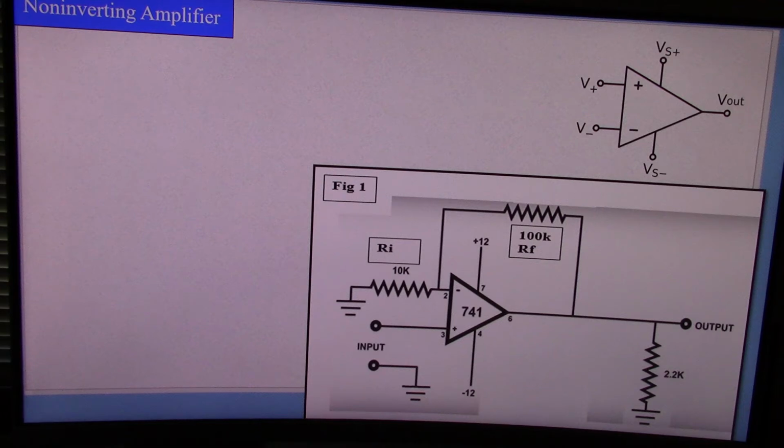So here's a circuit with negative feedback. You have this output here coming through this 100K resistor, feeding back to this input here. So with op amps, generally these numbers are the same. Like the non-inverting is 3 and the inverting is 2. Positive supply is 7, like that. But you really need to look at the schematic to make sure that they are correct.